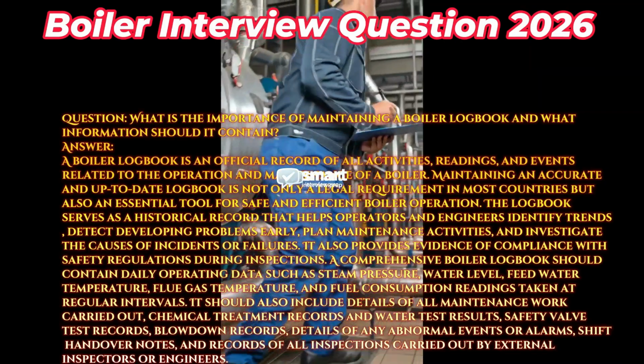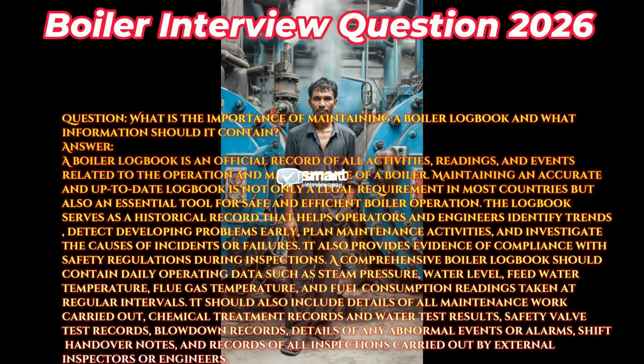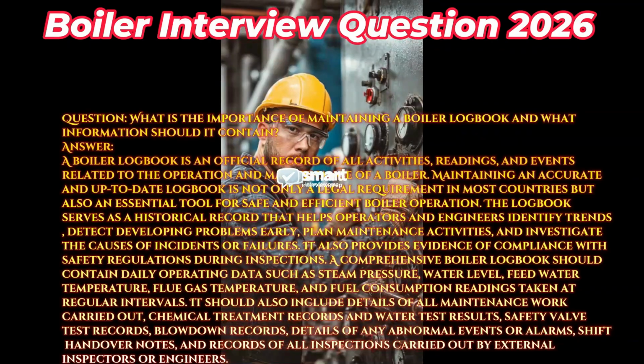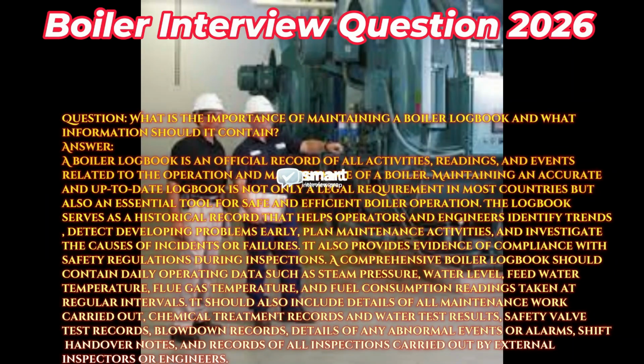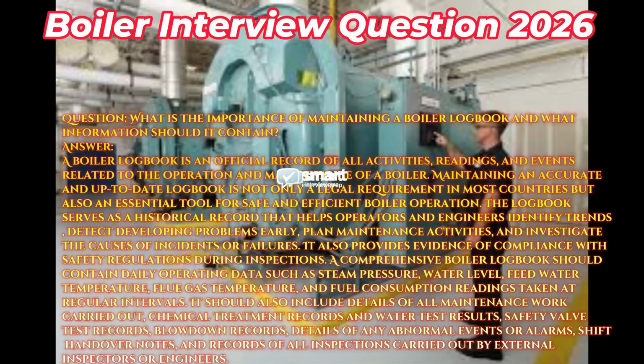A comprehensive boiler logbook should contain daily operating data such as steam pressure, water level, feed water temperature, flue gas temperature, and fuel consumption readings taken at regular intervals. It should also include details of all maintenance work carried out, chemical treatment records and water test results, safety valve test records, blowdown records, details of any abnormal events or alarms.